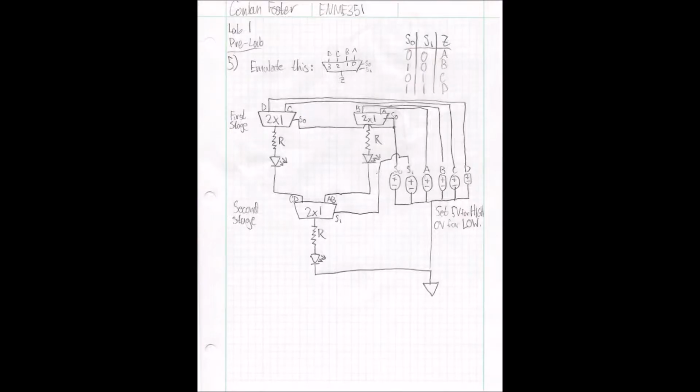So this circuit setup I've drawn is a series of three 2x1 multiplexers that combine to give a single 4x1 multiplexer. In order to accurately do that, we need 6 inputs. We need 2 selector inputs and then 4 inputs, A, B, C, and D respectively, that will represent the 4 possible results for a 4x1 multiplexer. With how it's set up now, any of these 4 can be voltage sources. They'd be 5 volts for high, 0 volts for low. So for example, if all A, B, C, and D were high, it doesn't matter what the selectors are, the return will always be high.